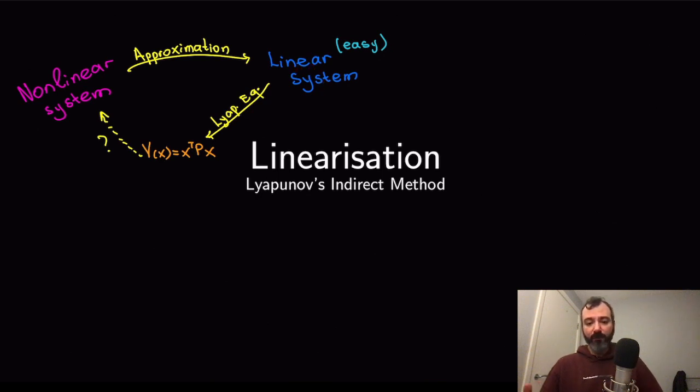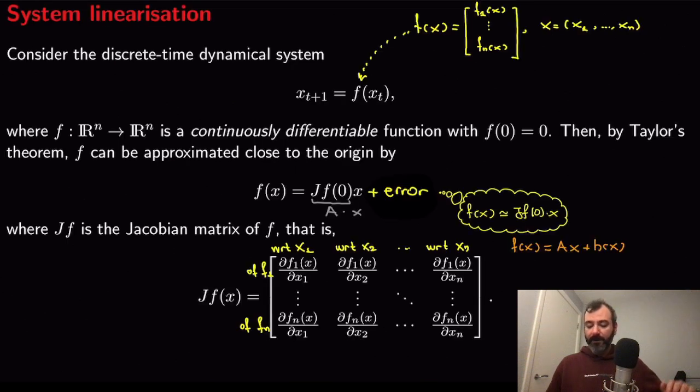We then solve Lyapunov's equation to determine a Lyapunov function for the linear system. And we want to see whether this quadratic Lyapunov function satisfies an LDC for the original nonlinear system over a certain invariant set. And the answer actually is affirmative under certain conditions. So let's start by having a look at the dynamical system.